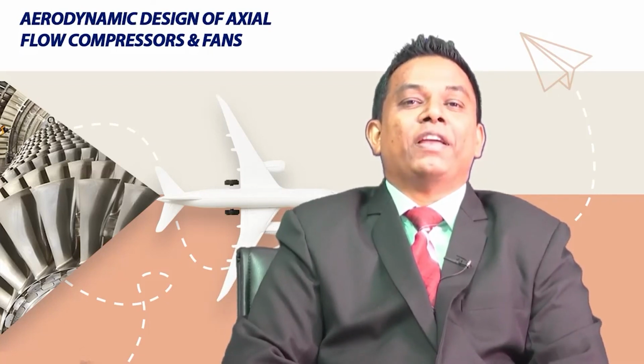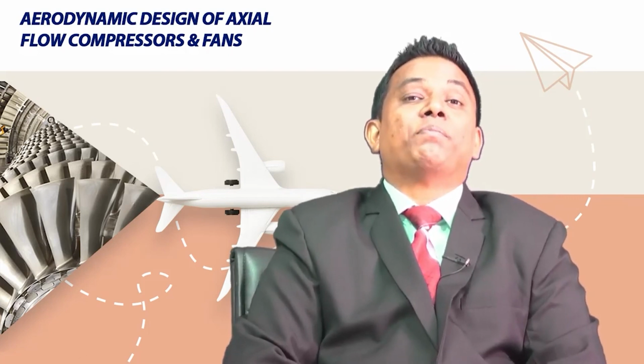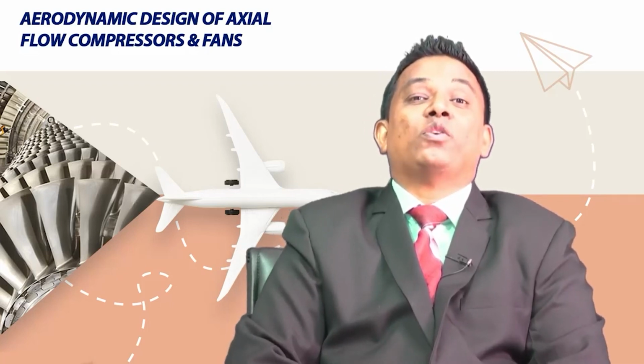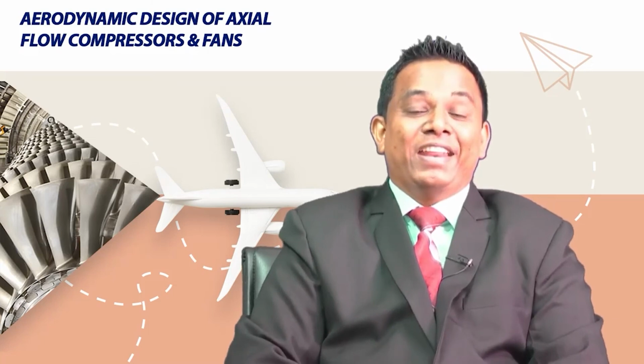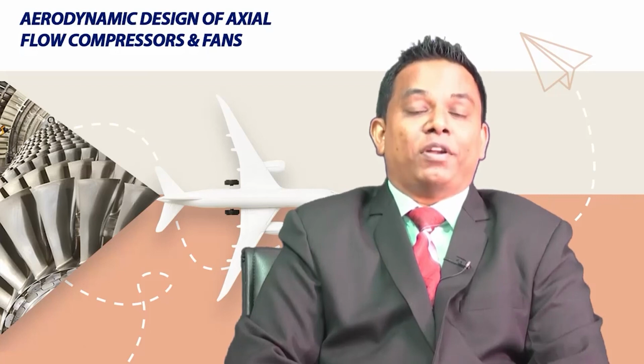We must realize the benefits of using this Excel sheet program, and we will soon get matured with using these Excel sheets, as whenever we do our design we will have the Excel sheet program with us. In the next lecture we will discuss, having covered delta P0 at the hub and delta P0 at the tip, that at 11 stations we need to distribute that delta P0 in a systematic way. Then only we will get a smooth curve for the blade, otherwise it will create trouble.